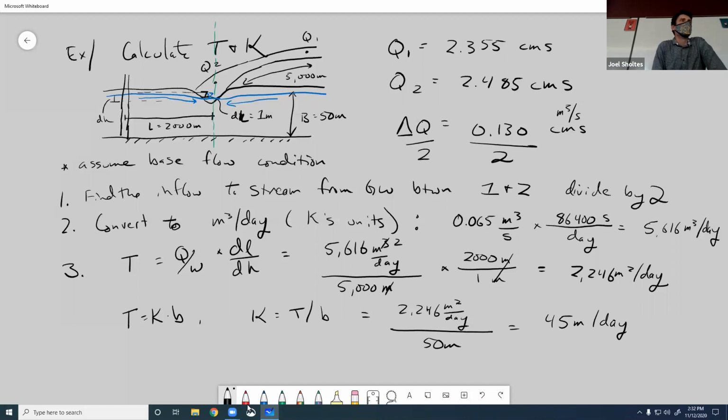So this is actually something you could do. You could measure flow rate. Flow rate is hard to measure in surface water. It's hard to really measure anywhere. So you have to have a really precise way of doing that. And the best tool we have these days is called acoustic Doppler profilers. They're usually boat mounted or even raft mounted. And they're able to basically tell you the velocity of these cells in the river over the 2 dimensions of that cross section. And they give us the most accurate estimation of discharge.